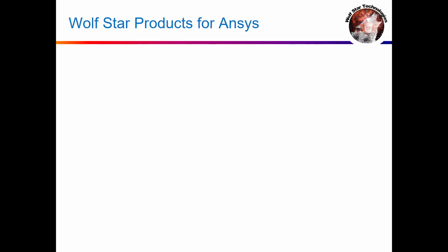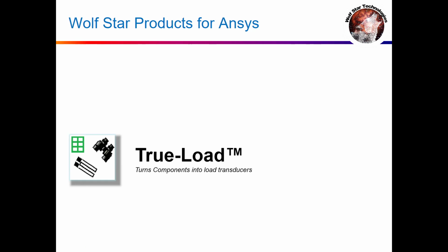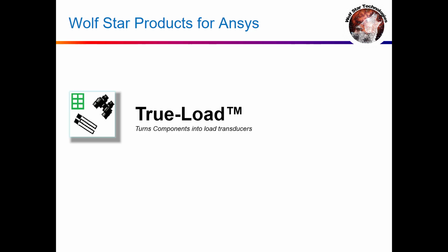The products from Wolfstar Technologies for Ansys are True Load, which is our flagship product, and this turns components into load transducers. We do this by placing strain gauges located on a component being driven by the FEA model and setting that up to be sensitive to certain unit load cases in the FEA model.